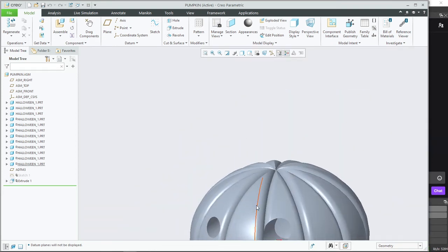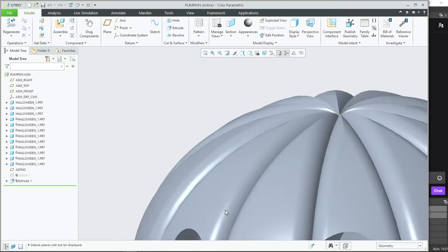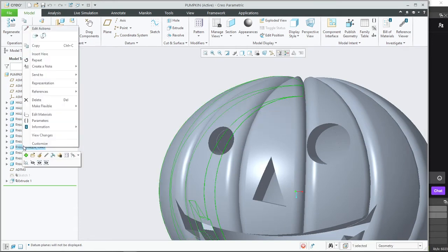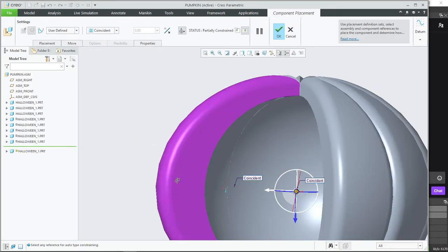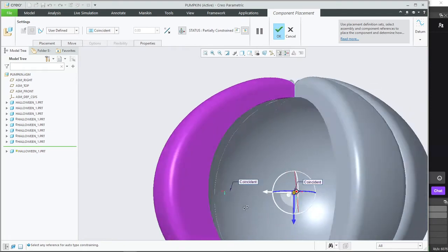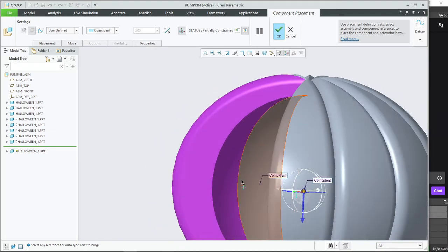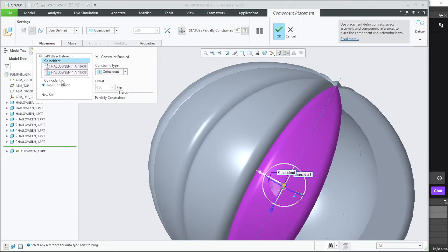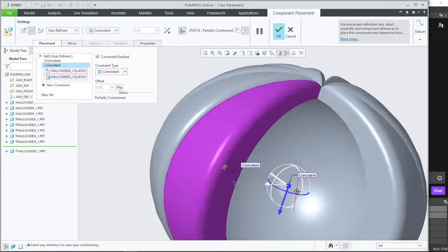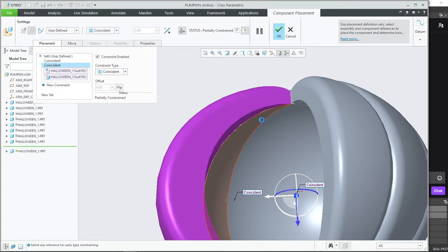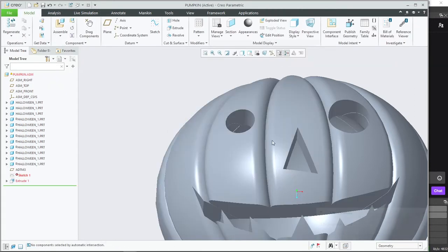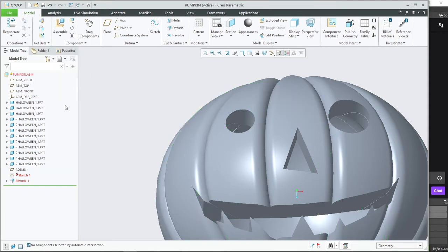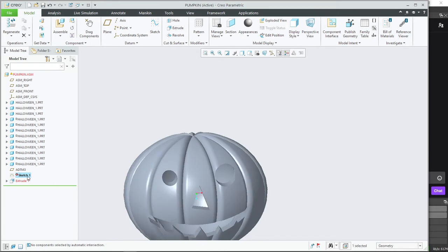Interesting. And is there a way we can fix that? Yeah, I would need to select the piece. First, I need to find it. I think it's this one. That's from this one, and edit its positioning options. So his positioning options are that he is coincident to this surface. See, placement, coincident. That one's good, but the ones before that have a little line. This one. So the one before that. That's one of the first ones. Sketch one has an issue.